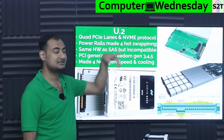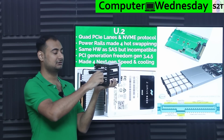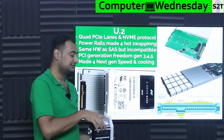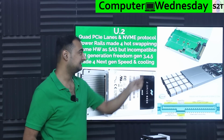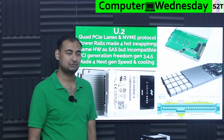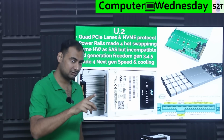Now, U.2 was designed for hot swappable, meaning it's a server system, meaning you're supposed to be able to do this sort of thing. Yeet hard drives into it, you're supposed to be able to put hard drives into it. If you do that with M.2, even if you made a physical caddy that can do that, you will fry the system. Specifically, if the port is active and you dumped it in, the likelihood of frying your M.2 is absolute. So to solve that, the power rails in U.2 were designed.